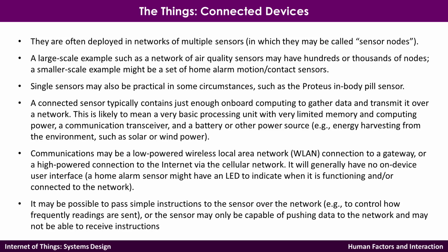In that kind of scenario, the centralized controller knows it is snowing because it has the full capability to access other sensors or weather APIs. So now it knows it is snowing, and then sends commands to the thousands of noise pollution sensors to perhaps increase the sampling rate, if that is what you want to do. So that is a scenario where you might want to develop your connected sensors in such a way that you can send a command back and change some type of settings, like frequency.